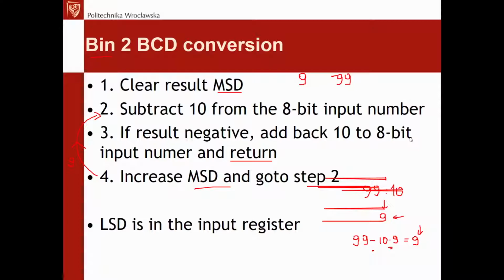Subtraction takes a negligible amount of time, but division and multiplication is a problem. So in case of microcontrollers, with this kind of conversion you always have to check what's the penalty, what's the price that needs to be paid for the division and for the multiplication, and then you have to decide which algorithm of the conversion you should use.